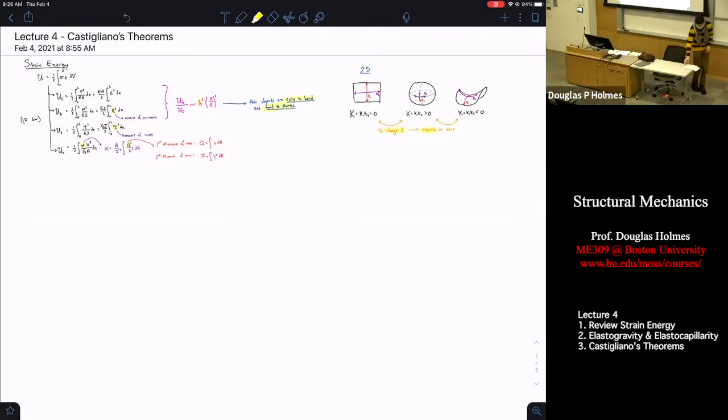I can take my sheet, hang it over the edge, oops, and it'll bend a ton. But if I just simply take my sheet and add a tiny amount of curvature to it, just like I'm lifting up the edges by a millimeter, and now it doesn't bend at all. Because to do so would require it to change its Gaussian curvature, which it's not going to do because that would require it to stretch, which is really too hard to do.